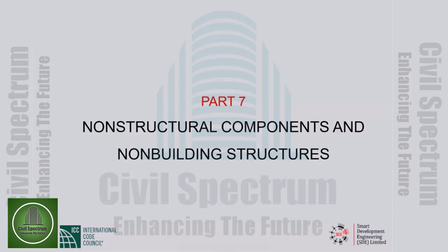A period less than 0.7 of a second means a more rigid building, and more than 0.7 of a second means a more flexible building. That's all. But I have no taste for those interstory drift limits under non-earthquake forces.